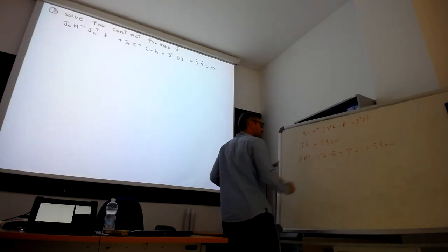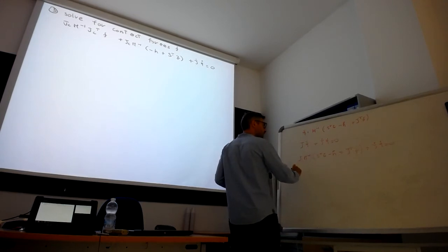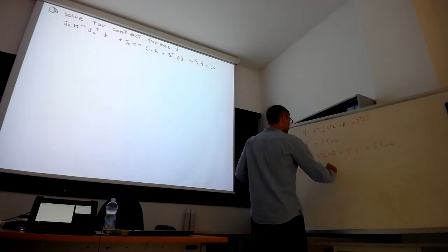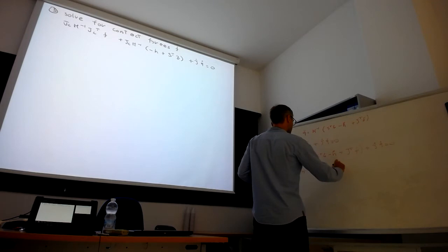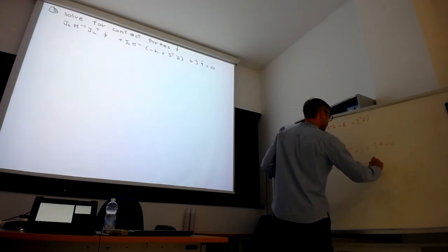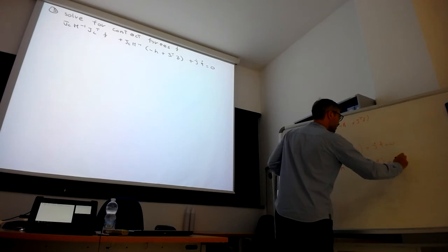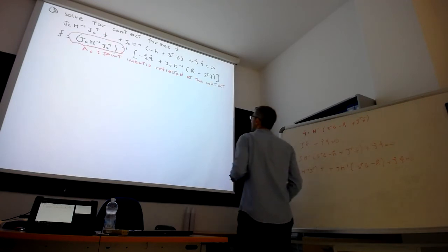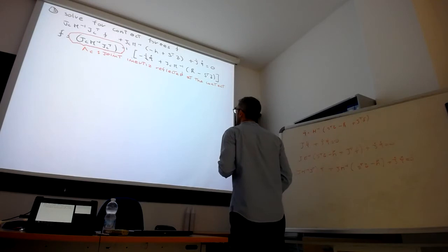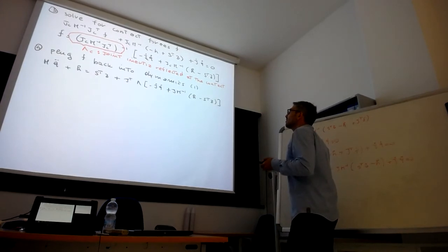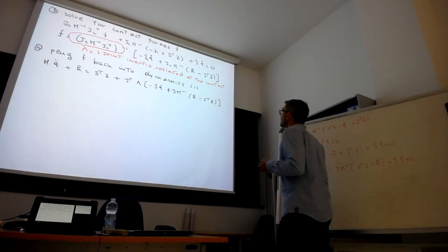Now we solve for the contact forces. So we get the contact forces, J transpose times f plus J M minus 1 times S transpose tau minus h plus J dot. And we can compute the contact forces. We already did that a while ago. We see that here we have the joint inertia reflected at the end effector, at the contact, sorry. And we can plug it back in the dynamics.